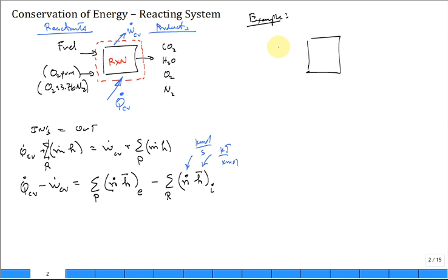So our fuel is just going to be carbon, and just say it's solid. In a typical system, you pulverize it, get it to a very fine powder, throw it into the combustion chamber. And I know that often we get the oxygen from air, but if I include air, I have to track along with the nitrogen. I think it's simpler. I know it's less realistic, but let's just say we have pure oxygen gas coming in. So I only have two reactants.